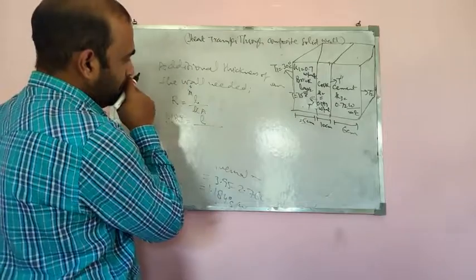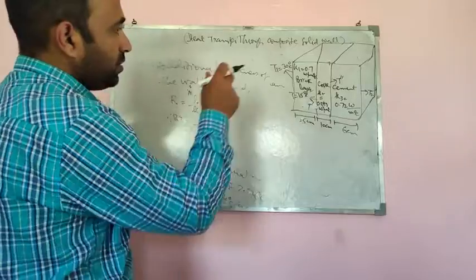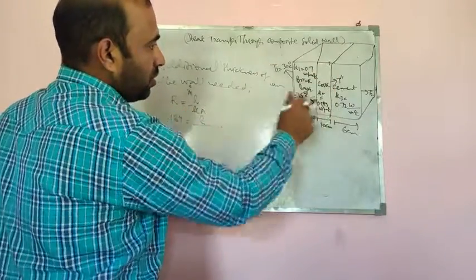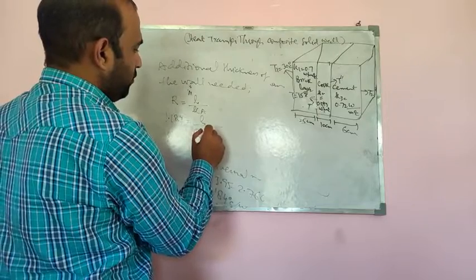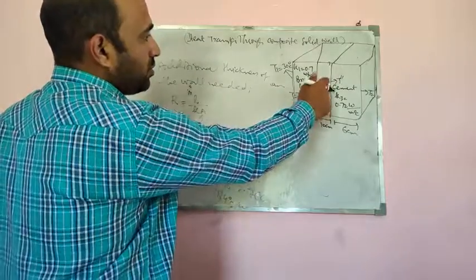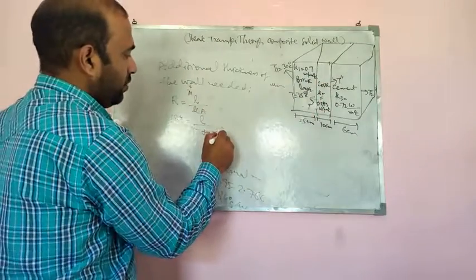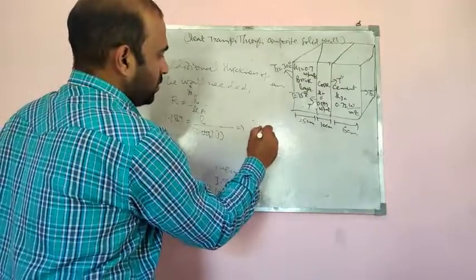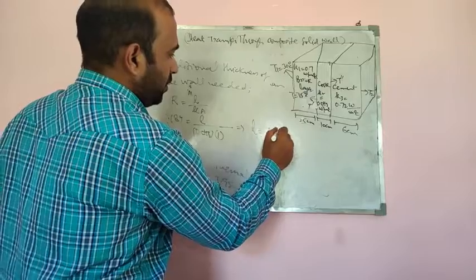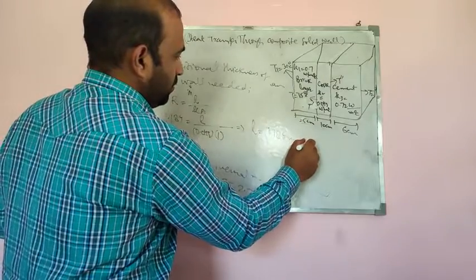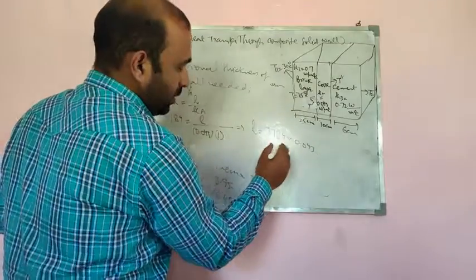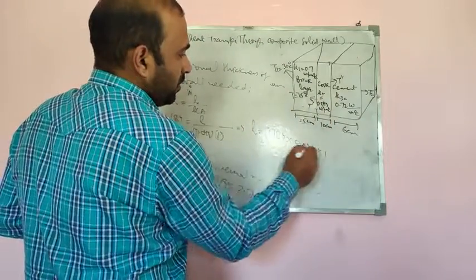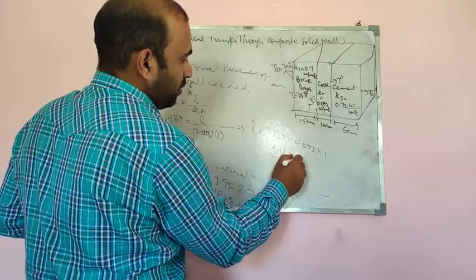Since we are considering the case of cork, K is 0.043, the thermal conductivity of the cork, multiplied by area, where we are considering 1 unit area. So L is equal to 1.184 multiplied by 0.043, multiplied by 1, which comes out to be 5.1 centimeter.